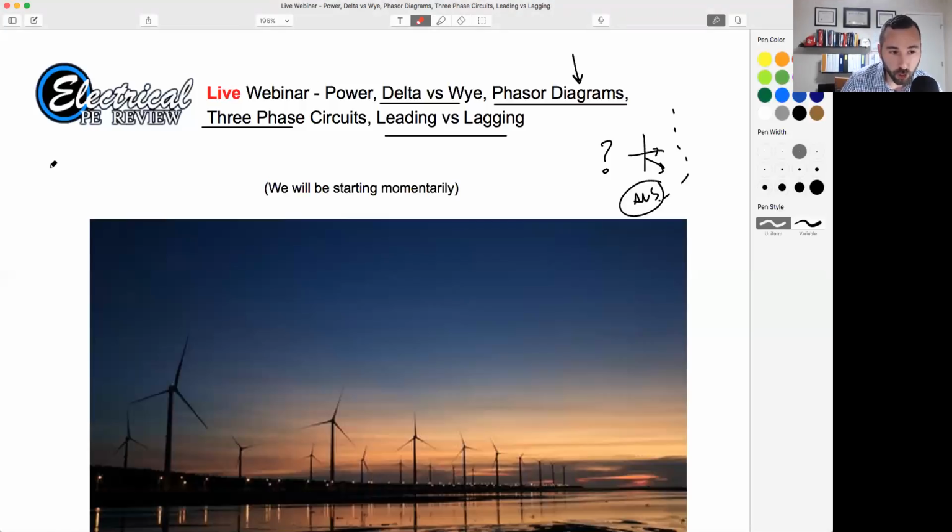So you always want to go back to V equals IZ, and that's Ohm's law. And of course, these are complex vectors, so I'll include my vector hat. And the other formula is single phase power. S apparent power equals VI conjugate. We can even say these are the phase values, right? Does everyone agree?